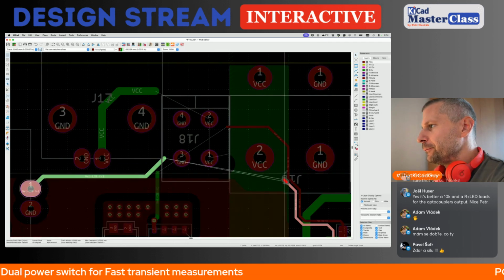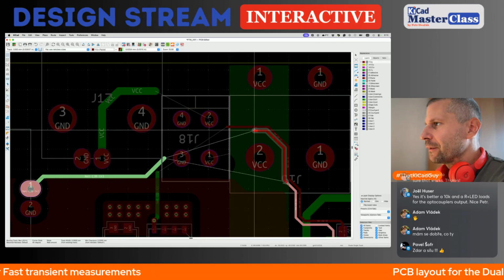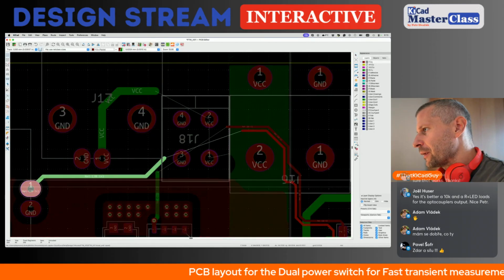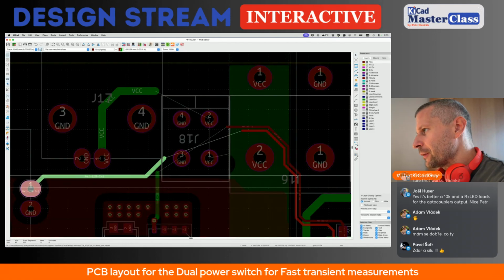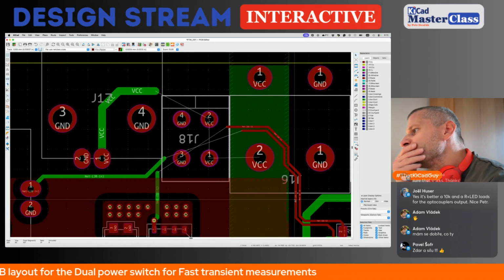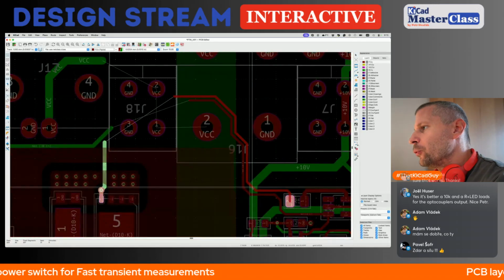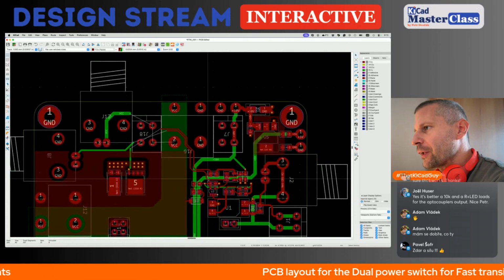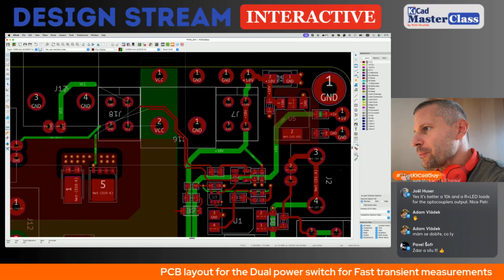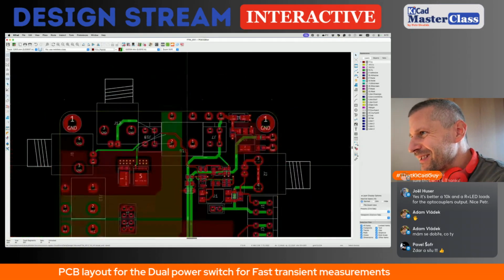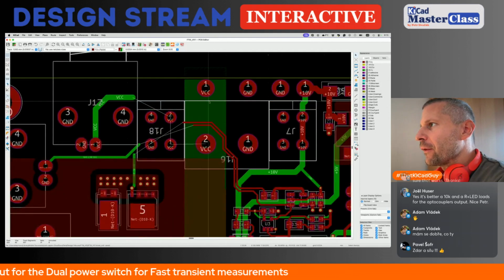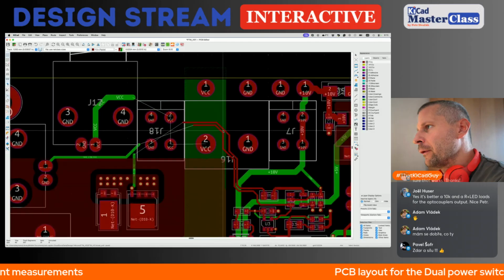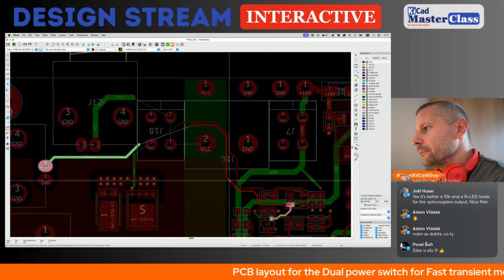Okay, so I'm working on routing these signals to interfere as little as possible with the MOSFET polygon. Plus, I moved this monitoring terminal slightly downwards because I want it to be aligned with the line of the other ones. Otherwise, it looks awful.